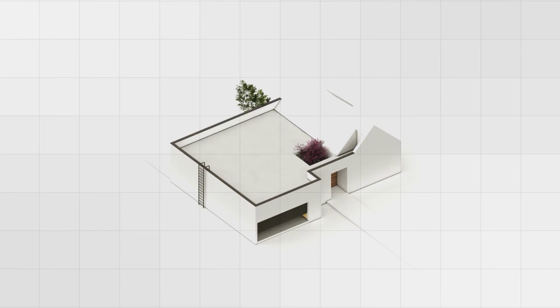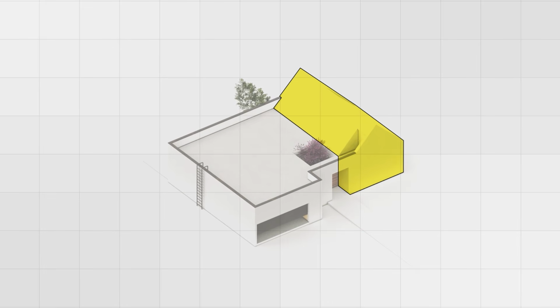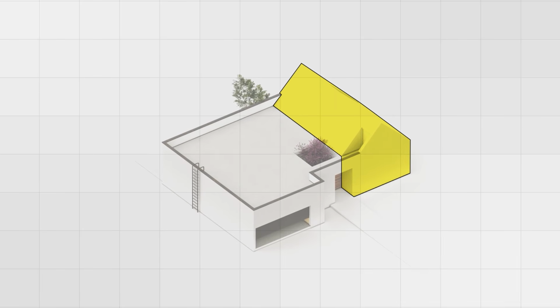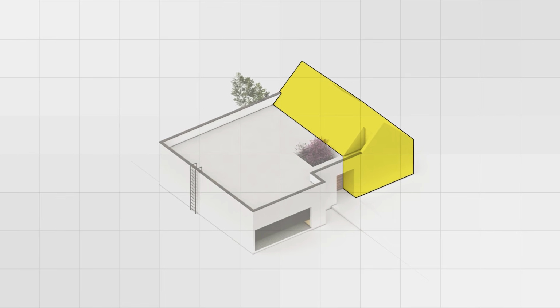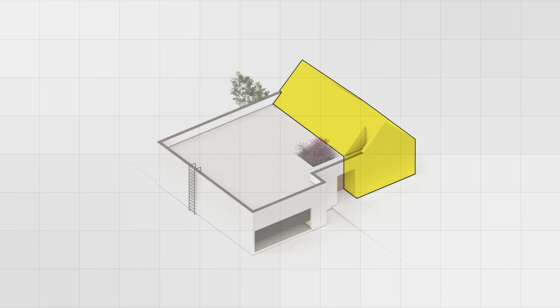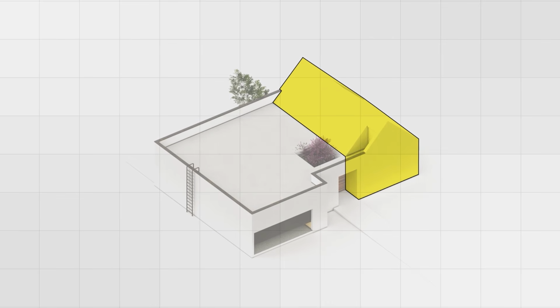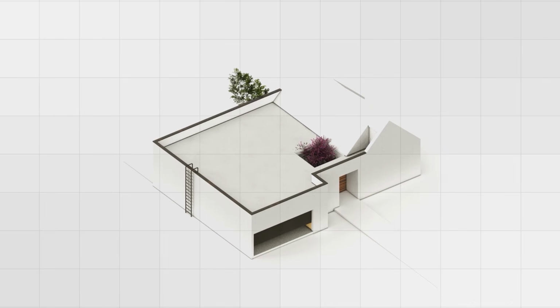The idea here is slightly different from a flat roof. Instead of just extruding a single surface, we need to think in terms of geometry that slopes and meets at a peak. So I start by defining the main edges of the A-frame based on the plan and the structural logic of the design. Then I create the guiding lines that represent the slope of the roof. Once those curves are in place, we can build the roof surfaces by connecting them and shaping the form step by step. At this stage, I'm not focusing on perfect detailing yet, but on getting the correct overall mass and silhouette, because once the main form is correct, refining the geometry later becomes much easier. And just like that, the roof starts to become a key architectural element of the villa, and the overall design begins to feel complete.